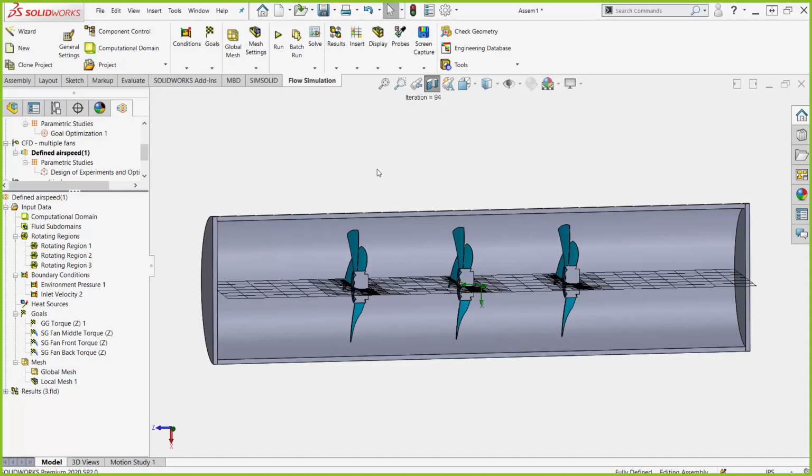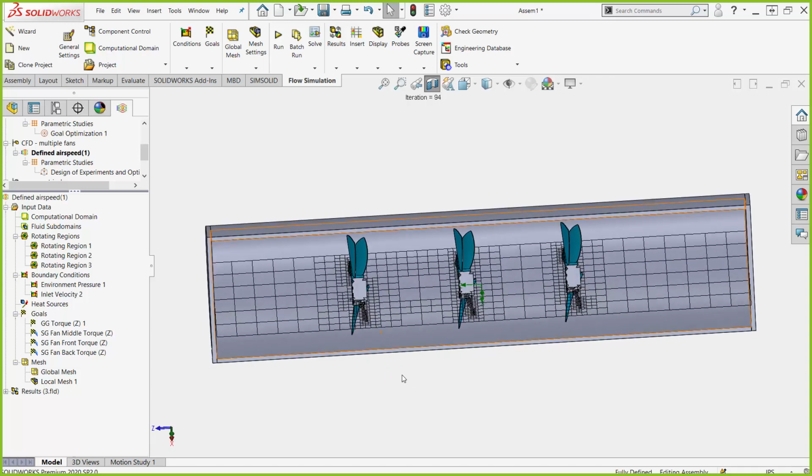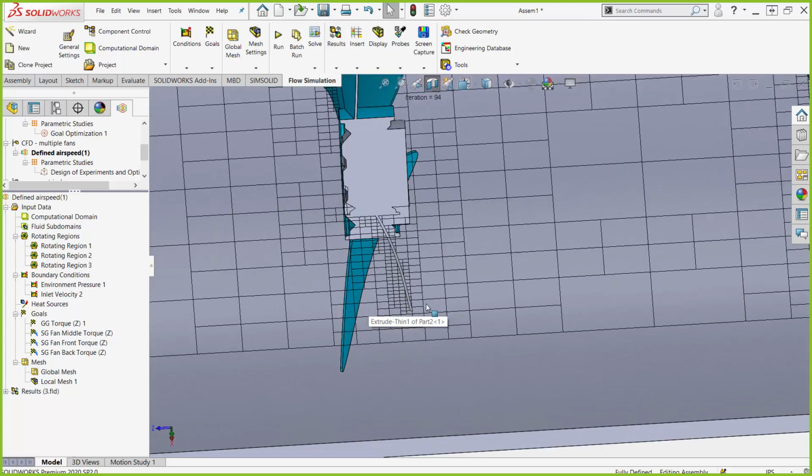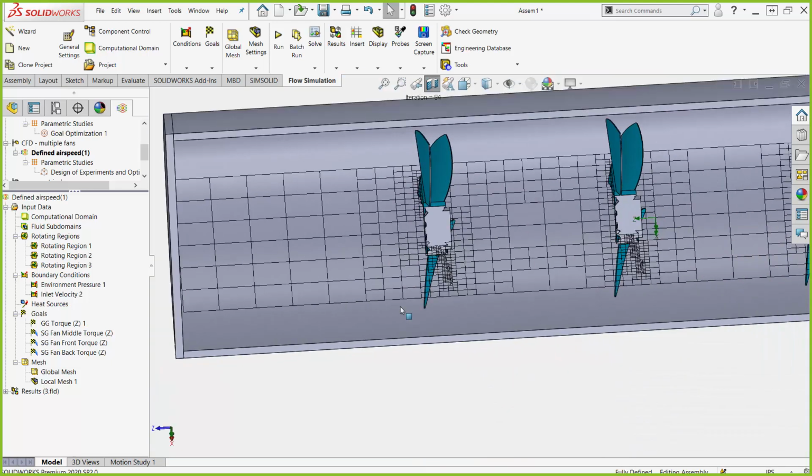So the most sensitive thing absolutely is mesh. You could do a terrible mesh and a 100-second solve time and still solve reasonably quickly. So mesh, absolutely the critical thing that increases solve time. Now, because of fan blades generally being thin, and then combining that with the time-based analysis, that's where solve times tend to blow up. So that's why we keep times, like amount of rotations, lower, because we're required to have that mesh higher. So I'll say that again, mesh is the really critical thing.